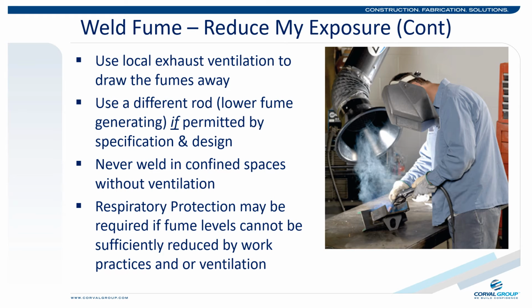It may be possible to select a different rod that generates fewer and less toxic fumes. This is not always possible, as rod type is often specified and substitutions may not be allowed. Typically, it doesn't hurt to ask.